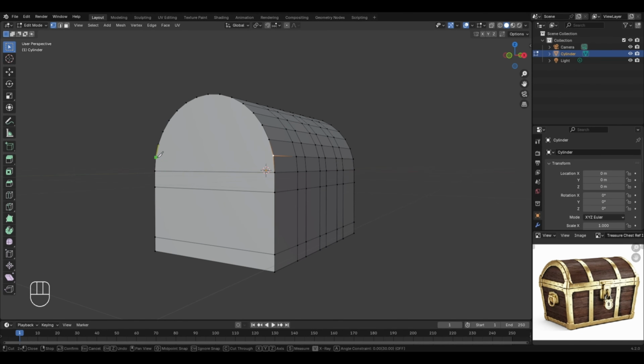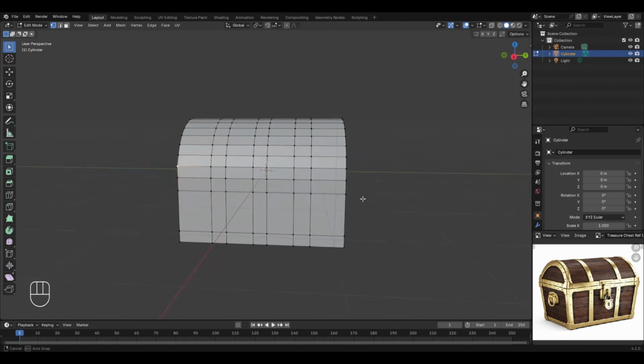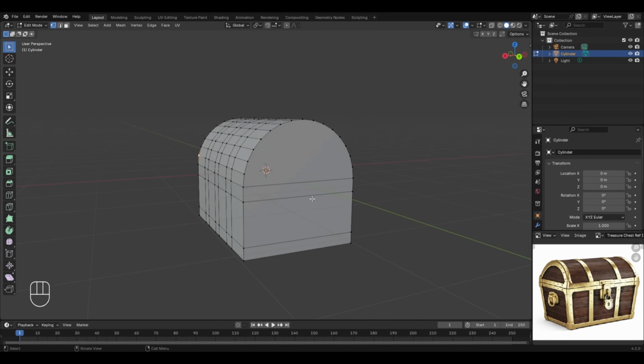Then first of all, I'll take this tool on that particular vertex, then left click, drag the cursor away, and we'll take this point to the other vertex. Then left click and press the enter button. And by doing this, we are now having both of these points connected with each other. Now let's do the same thing with the other side also. So press K to enable the knife tool, then select this vertex, and after that, left click to select the other one. Then press enter to confirm, and with this, both of these vertices are also connected together.